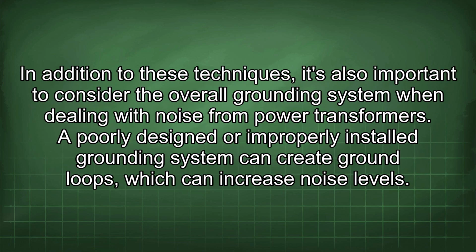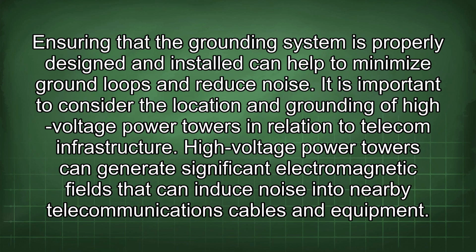In addition to these techniques, it's also important to consider the overall grounding system when dealing with noise from power transformers. A poorly designed or improperly installed grounding system can create ground loops, which can increase noise levels. Ensuring that the grounding system is properly designed and installed can help to minimize ground loops and reduce noise.